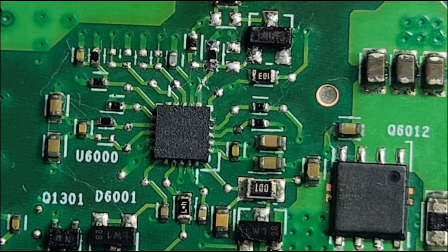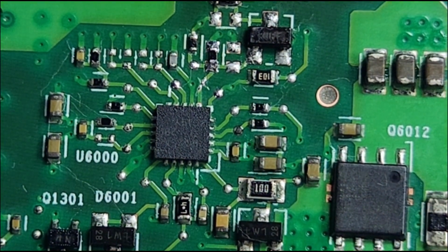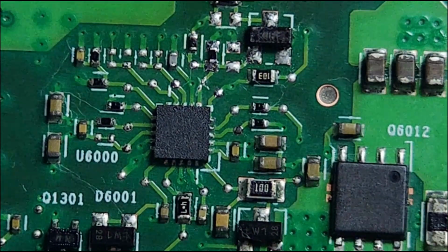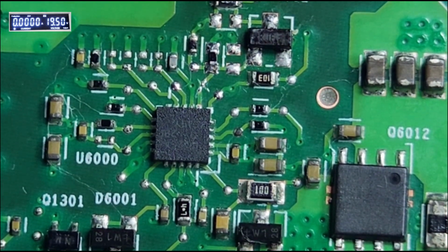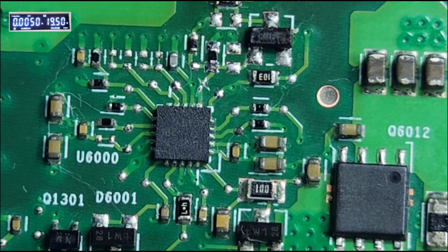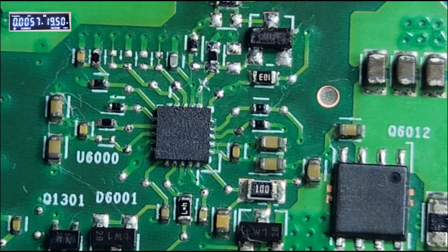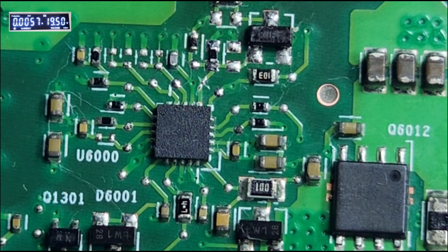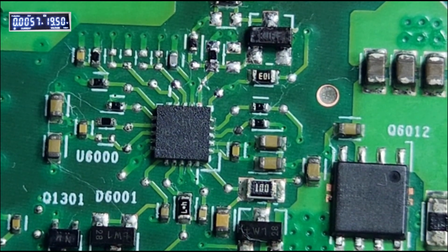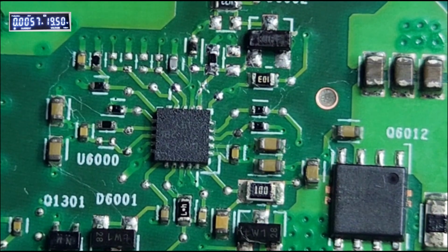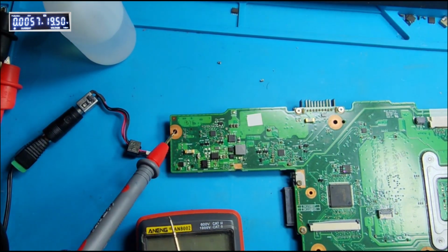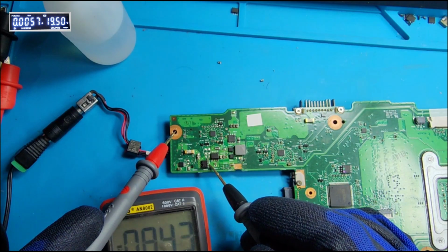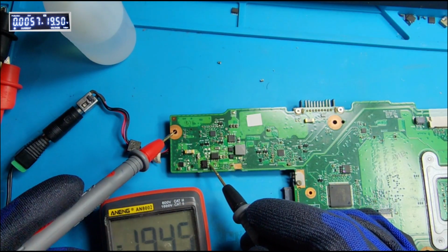Okay, now let me connect the adapter. So I'll just turn on the DC power supply as well. Okay, now the power supply is visible to you now. Let me connect the adapter. Yes, and the adapter is connected. Now you can see the amperes drawing around 5 milliamps. Okay, now let me see whether we have a main power rail. So, okay. Yes, we do have the main power rail.